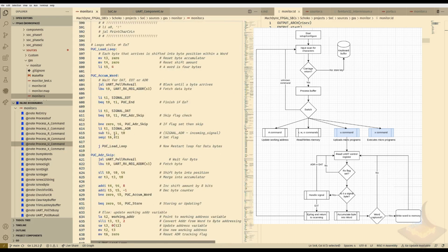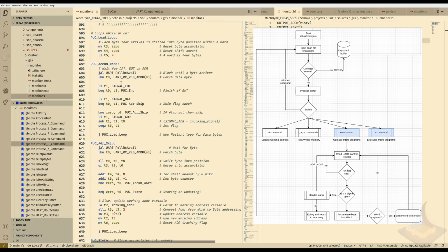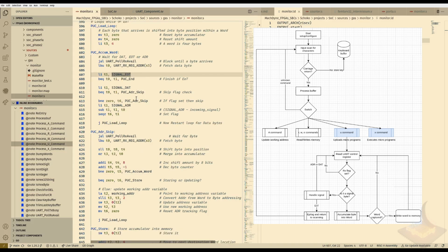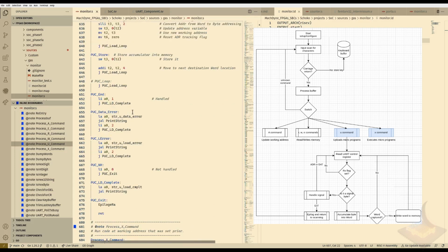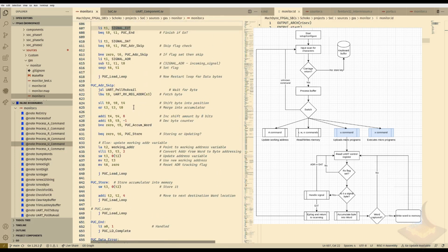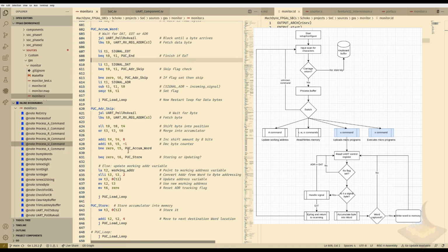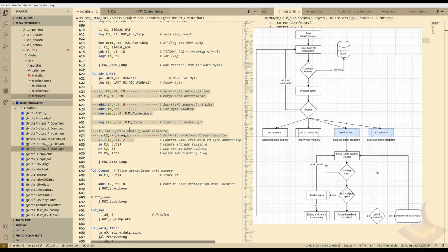And then it falls into this large loop that's going to go around in circles looking for one of three signals. Now this is a half software-defined protocol. So the client is going to send data and will need to have a delay between each byte. Otherwise, you'll upload junk and garbage half the time. And I'll show that again in the uploader. Basically, it's going to take the incoming stream and look for either signals that are coming in or data that's coming in. And it'll take that data and pile it into words. This is uploading code. It just doesn't upload random things.